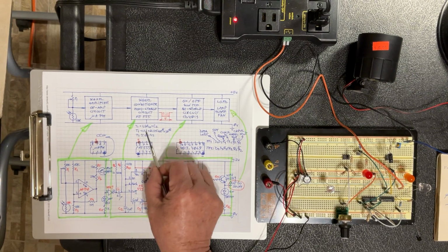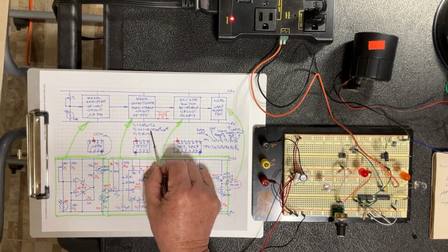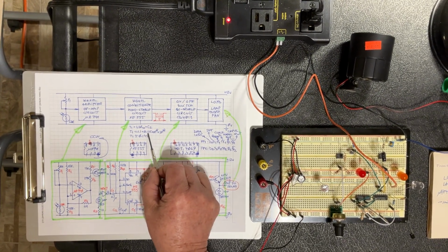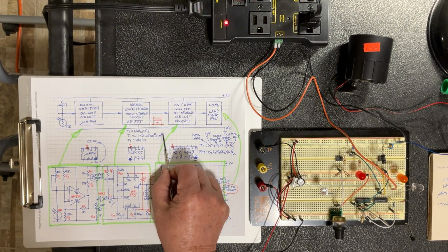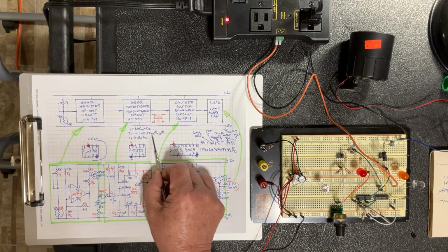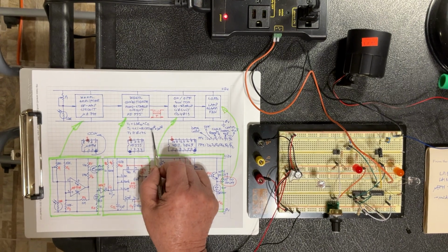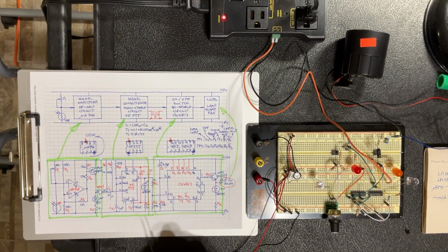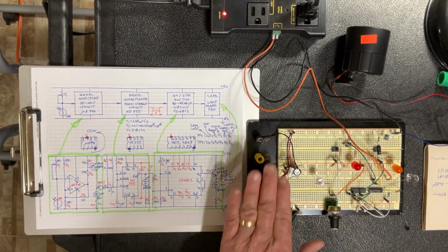If I replace with the values, 125 kilo ohms, I convert it to mega ohms, 0.125. Why in mega ohms? Because I need the 10 to the 6th power to cancel the 10 to the negative 6, which is the micro for the 1 microfarad here. I only need to do this very simple calculation, no need for the pocket calculator at all. And I get something like 0.14 seconds, which is 1/7 of a second. This is the duration the amber light stays on.